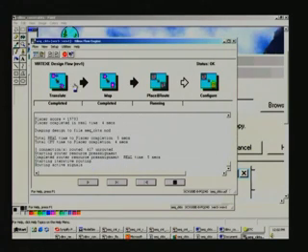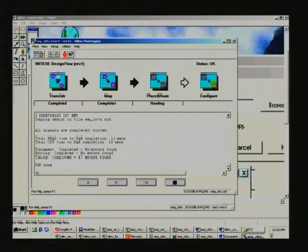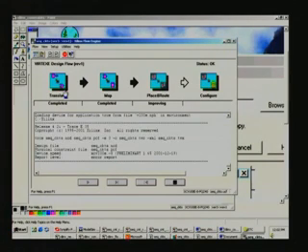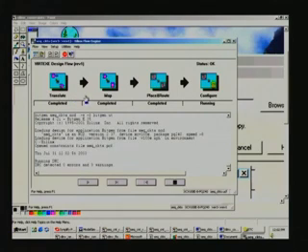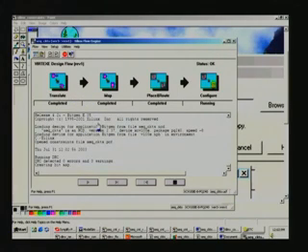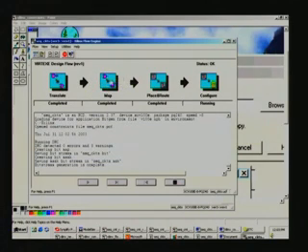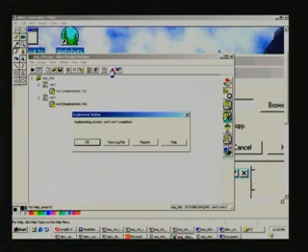Right now, what you see is that this is over and this is also over. The first one is called translation, which translates the input .edf file into a format compatible with its own tool, and then actually maps the different primitive cells, including the device, and within the device all the primitive cells which we have already seen.